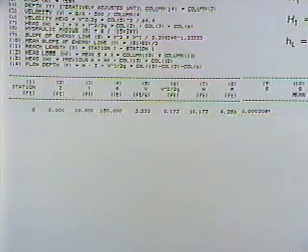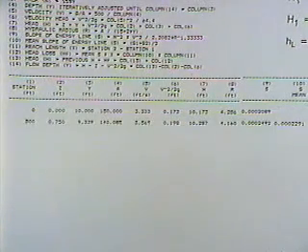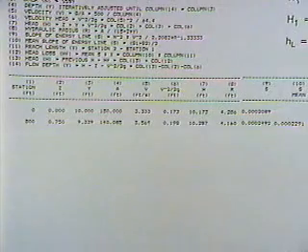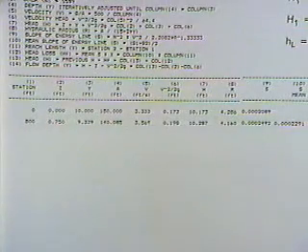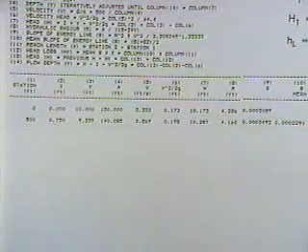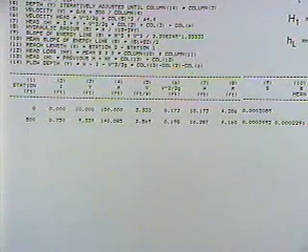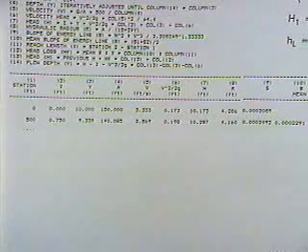So once you got the depth, you can compute everything from simple equations. Now the problem is we don't know the depth. And so what we're doing here, the first line is just to give us basic data, and so we're working upstream now. So at the end of the channel where it empties into the river, the depth is 10 feet. I don't know the depth.